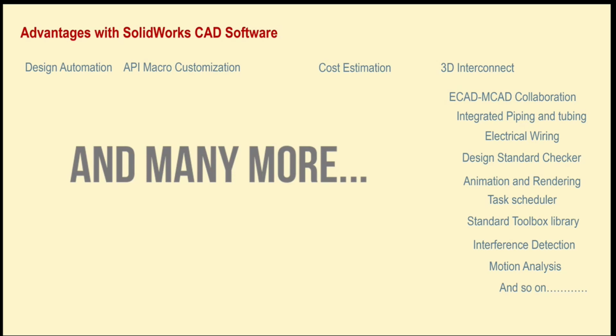And next we have interference detection. So many people are frustrated with designs with interferences. So SolidWorks interference detection will just help you, and you will feel very encouraged by using it. It will give you an Excel report simply telling you which components are interfering, what the volumetric interference is, and how you can take actions to reduce them. So it is cool.